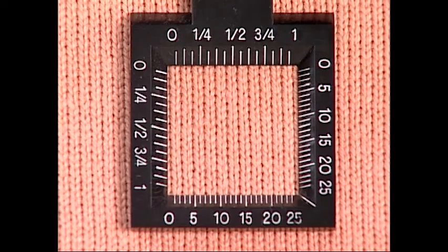A typical apparel single knit sweater fabric would have a stitch count of 18 by 12, which would be 18 courses by 12 wales. The reason knitters list courses first is because it's a direct measure of the production for that machine for a given fabric and relates to the cost of production.